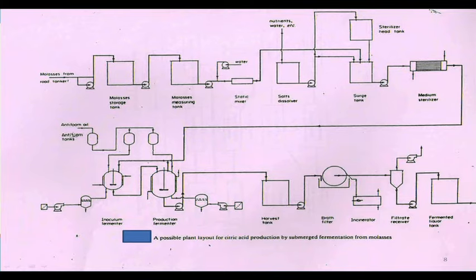And here you can see the antifoam oil tanker. This has sterilized antifoam oil, which we use to subside the foam. This antifoam tanker is also connected with the mechanical seal I told you about when I explained the bioreactor. The shaft of this mechanical seal is also lubricated with the help of this antifoam oil, so that friction between the shaft and the mechanical seal is minimized.